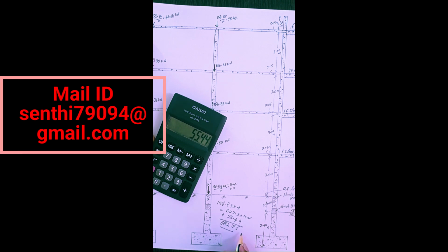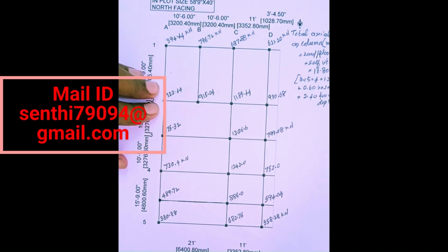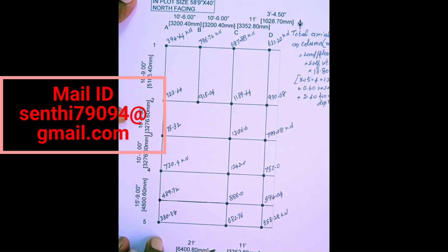So 682.76 kilonewton is the axial load of this central column. This is a drawing which indicates the axial load of the column, including loads from all the floors and the self height of the column. I have written it near to every column position.